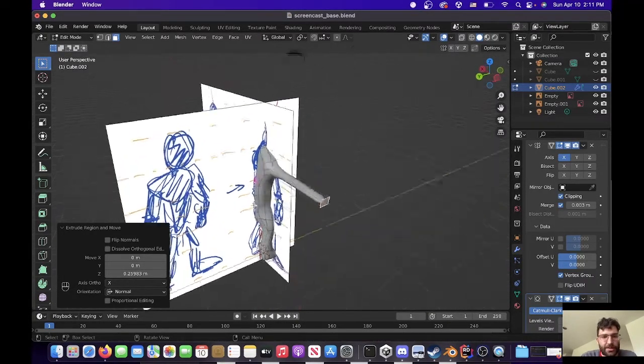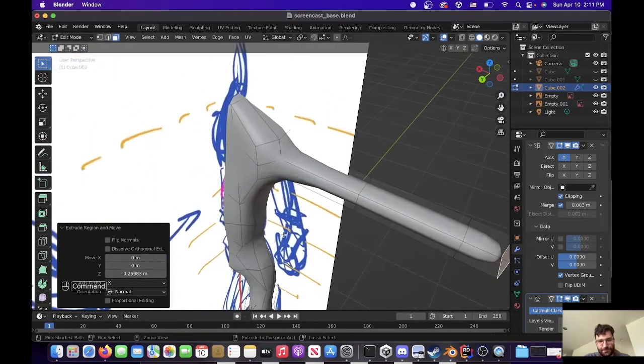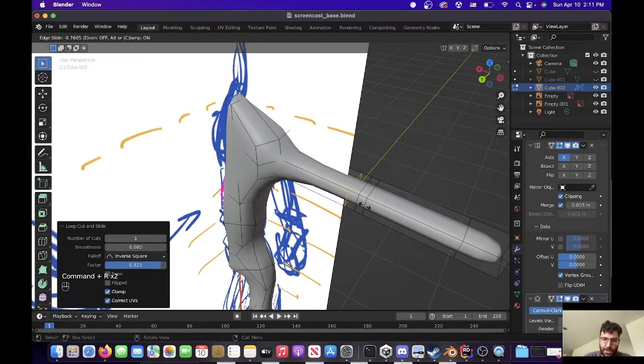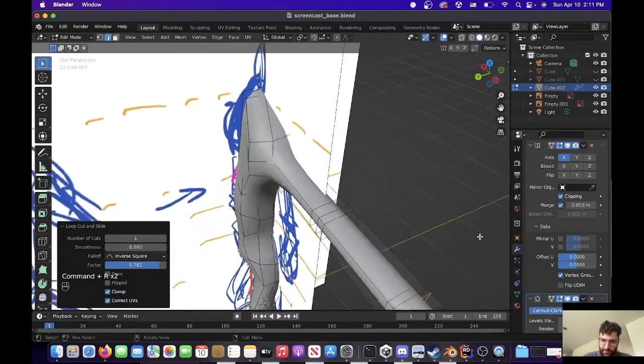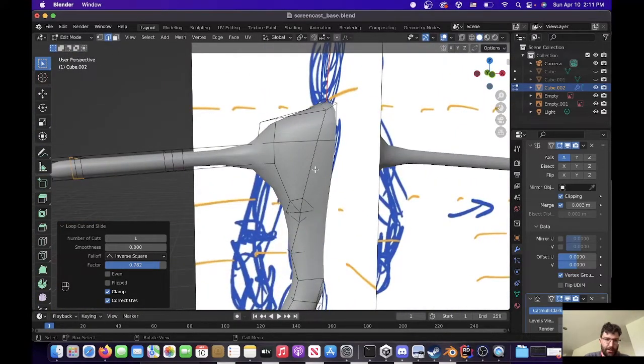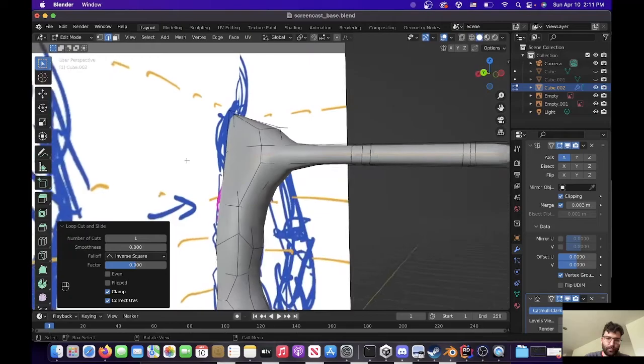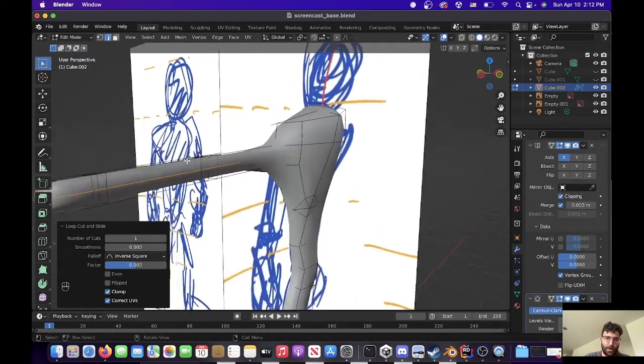What is not okay is that if we add bones to this, we're going to get some weird creasing right here. So we actually have to make more loop cuts to increase the resolution of the geometry near the joints. So I'm just going to add lots of loop cuts. And then maybe, can we do one? Yeah, this is jank, but it'll work. Now I've got it sort of like that. Okay.